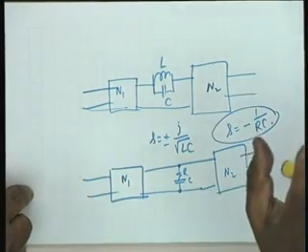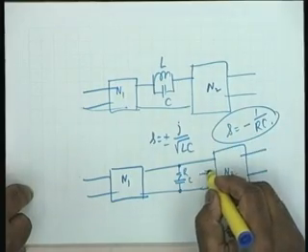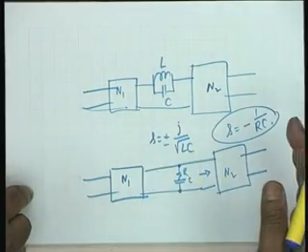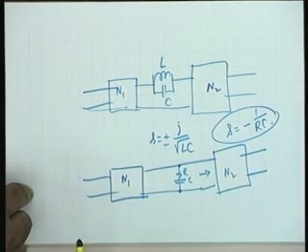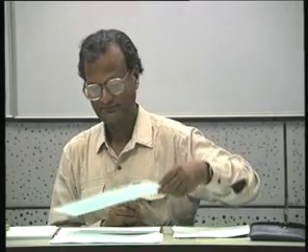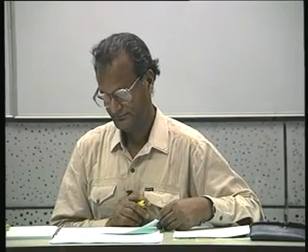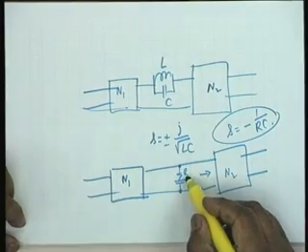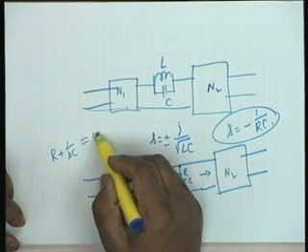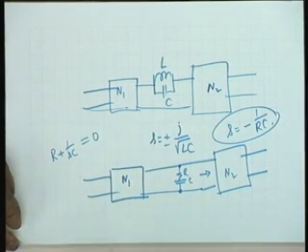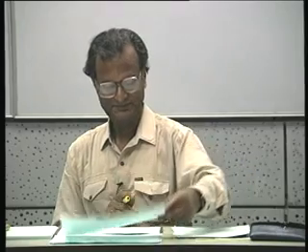Once again, that qualification should be there, that the impedance looking to the right of this should not also have a zero at the same frequency. If it does, then of course that is not correct. Pardon me? There should be no j here, because this impedance is R plus 1 over SC, and this will be 0 when s equal to minus 1 by RC. No j. Alright?